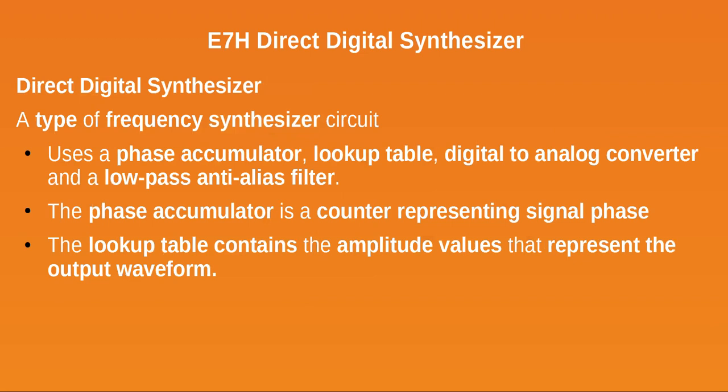In the direct digital synthesizer, they basically simulate the sine wave by what they call a phase accumulator, and it just generates steps of the waveform cycle.